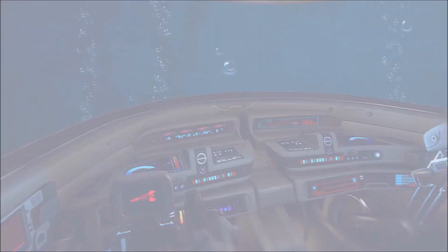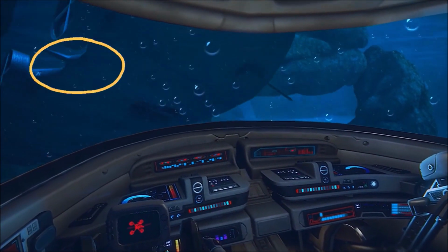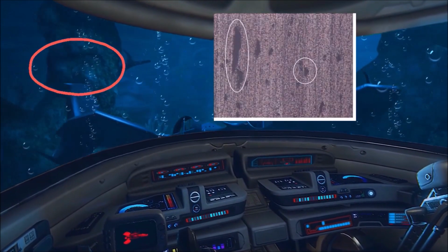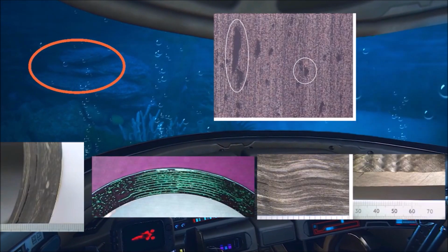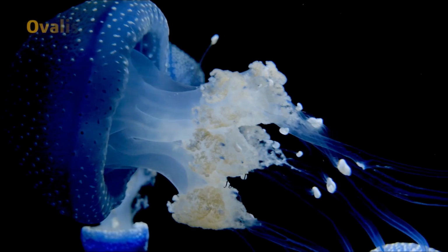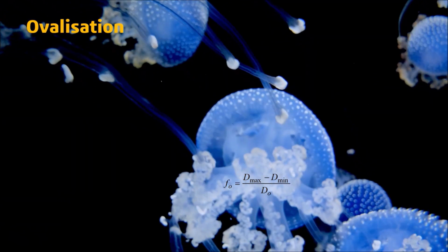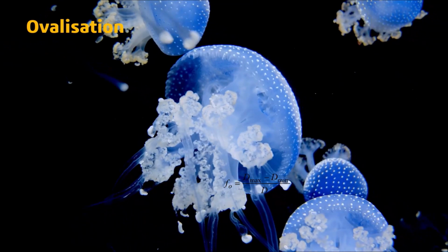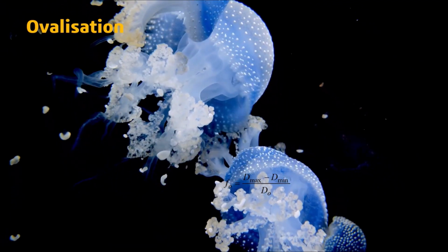The main defects found in composite tubes are ovalization, porosities, delaminations, and fiber waviness. Any geometrical deviation from cylinder, whether it is out of roundness, which may be caused by creep during cure. Since I work in offshore underwater pipeline design, we as designers have to design against collapse.